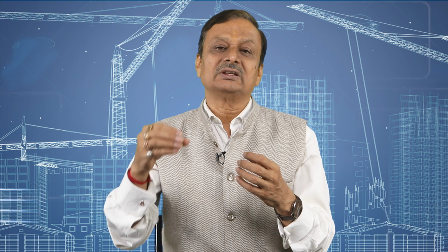Second is the minimum voids method. In this method, the voids of the coarse aggregate and fine aggregate are determined separately, and the quantity of sand used should be such that it completely fills the voids of the coarse aggregate. Similarly, the quantity of cement used should be such that it fills the voids of the sand. So, a dense mix having minimum voids is obtained.